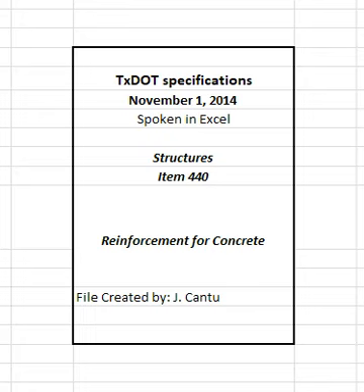Protect threaded male or female connections, and ensure the threaded connections are clean when making the connection. Do not repair damaged threads. Mechanical coupler alternate equivalent strength arrangements, to be accomplished by substituting larger bar sizes or more bars, will be considered if approved in writing before fabrication of the systems.